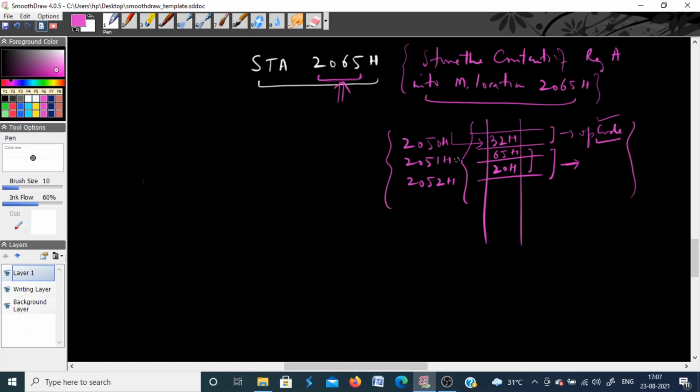The processor will first fetch the opcode, decode it and execute it. It will come to know that it has to store the contents of the accumulator into a memory location, the address of which is specified in the next 2 locations. So first is the opcode fetch, of course, which requires 4 T states. What is the second operation here?